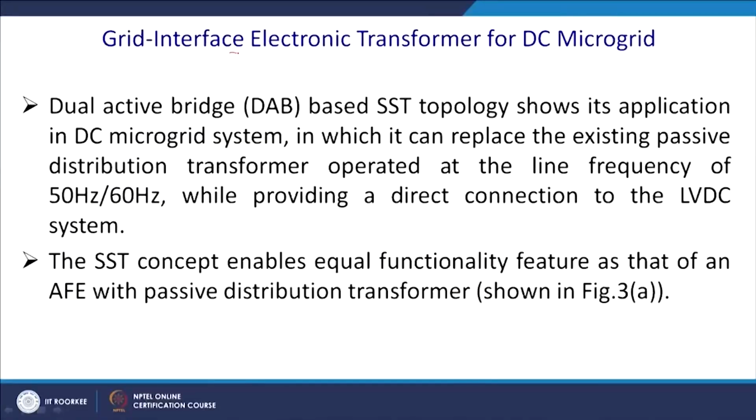Now, grid interface electronic transformer for DC microgrid. It is quite an interesting new topic. Dual active bridge or DAB based solid state transformer shows its application in DC microgrid, in which it can replace the existing passive transformer, which is a dumb transformer